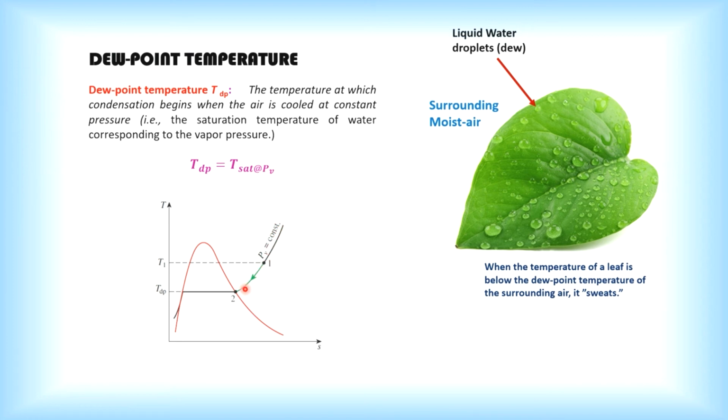So at constant pressure, when the temperature drops, especially when air flows across this colder surface, at the surrounding pressure, which is constant, the temperature will drop until it reaches this dry saturated vapor line. Any further heat removal will cause it to move inside the dome.